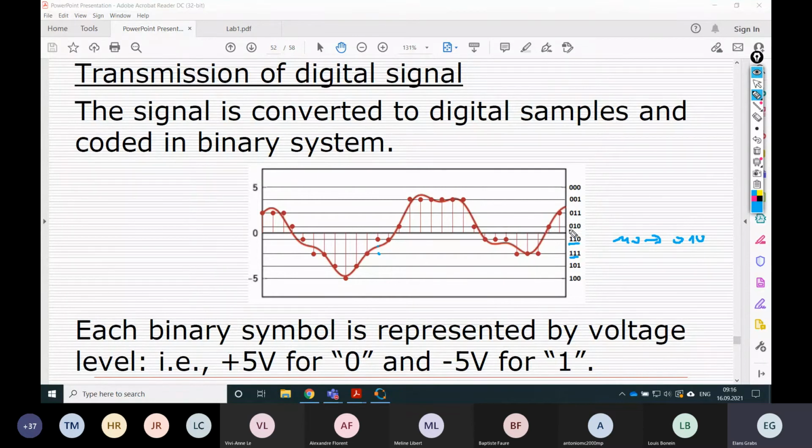Then we'll get to this point: instead of this point, we'll receive this point. If one error happens and 110 is converted to 100, then this will happen. So in short, this minimizes the actual change because of the errors that can possibly happen in this binary code during the transmission. So we'll get as close to the original point as possible if we use gray mapping. That's why it's used here.